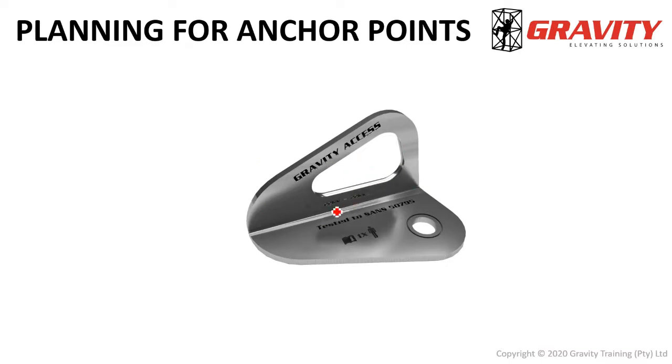Typically, if it has a 25 kilonewton rating in the parallel direction, it'll have a reduced strength of about 15 kilonewtons in the perpendicular axis. Okay, so be very careful. Don't use your anchor points in a direction that is not approved or not of sufficient strength in your applications.